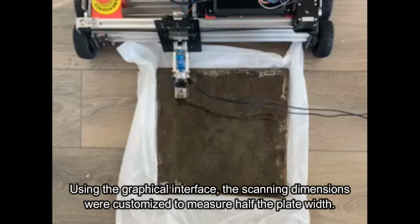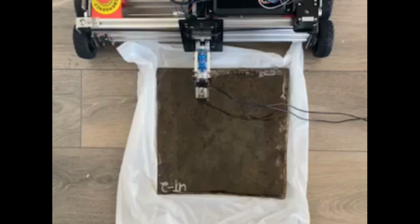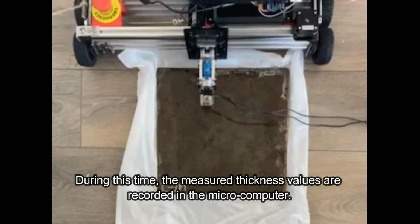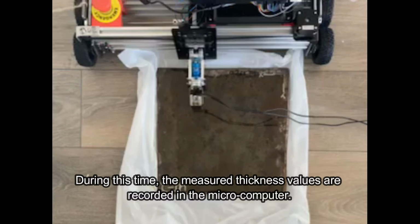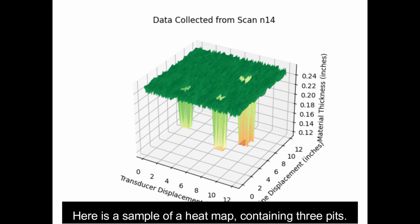Using the graphical interface, the scanning dimensions were customized to measure half the plate width. During this time, the measured thickness values are recorded in the microcomputer. The data stored in the microcomputer is then used to populate a visual heat map that can illustrate areas of risk. Here is a sample of a heat map containing 3 pits.